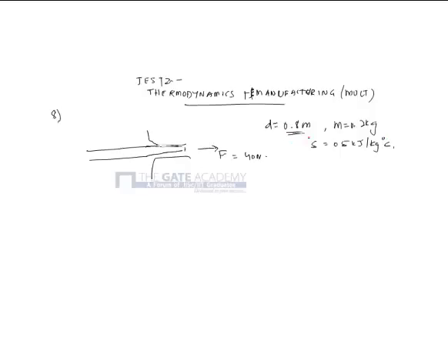And what is asked is the maximum increase of the average temperature of the wire. This is what is asked. Okay, so the work done by this force is basically F into D, and remember that in the problem it is given that D is the displacement along the force, so we can directly multiply it, otherwise we need to take the cos between force and the displacement. So force value is 40 Newton, this is 0.8, so the work done is 32 joules.